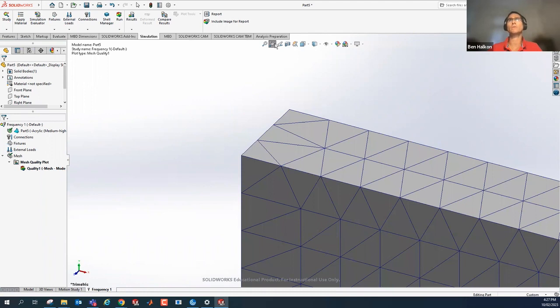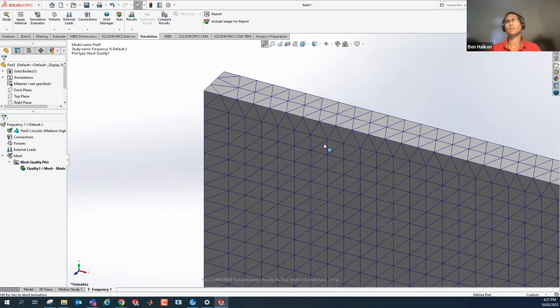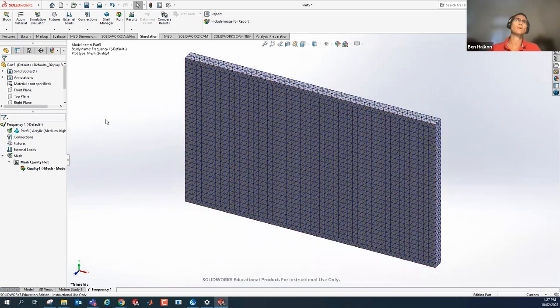They're tetrahedral elements, which are the easiest types of elements to build a mesh from. Quadrilateral elements are more challenging, hexahedral elements. But again, for the sake of a simple analysis of a simple structure, these elements will be perfectly acceptable. We can then run the analysis, and it's going to take a while to complete. You can see the timer here, or the activity monitor here, as it runs through the solver.